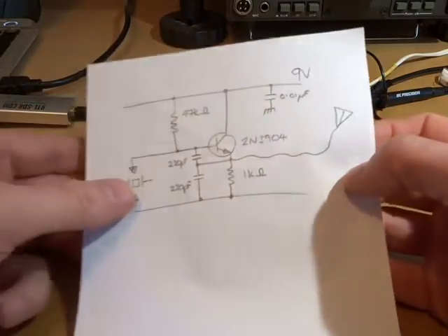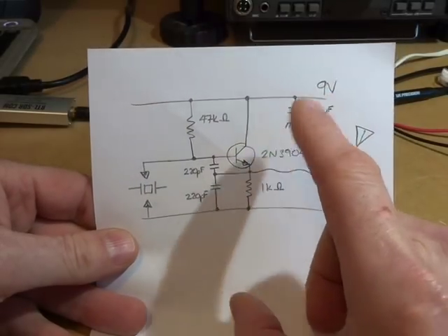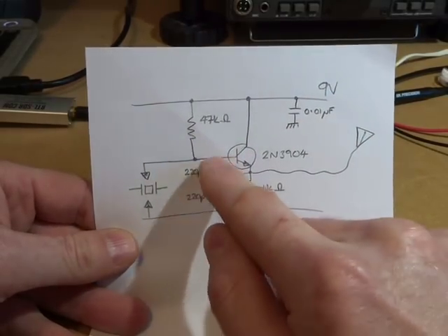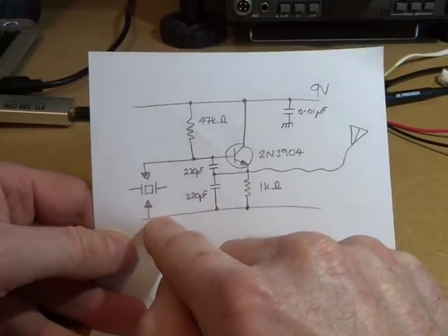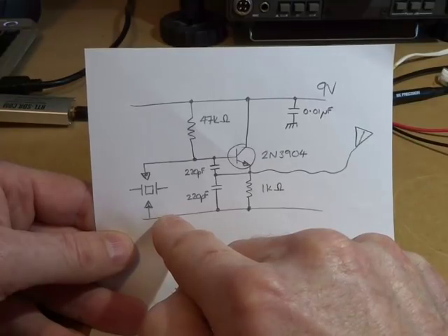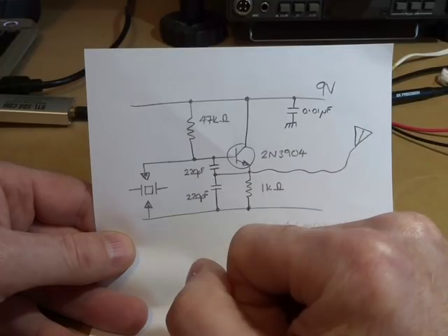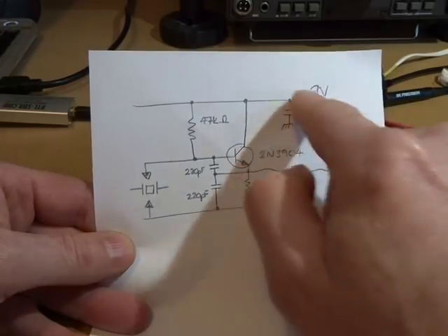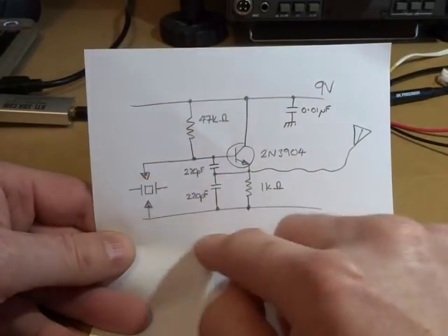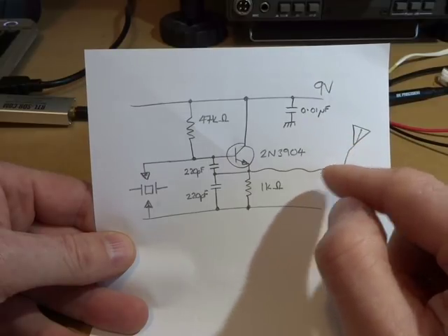I'm going to do that in 2 ways. I'm going to start by using a simple Colpitts oscillator here, using a 3904 running off 9 volts with some simple biasing. There go our split capacitors for the Colpitts, 2 220 picofarad capacitors, and then between the base and earth will be our crystal under test. So I'm going to grab those 100 crystals I got from China, and we'll run them through this little test oscillator, and then using a little fly lead, loosely couple this through